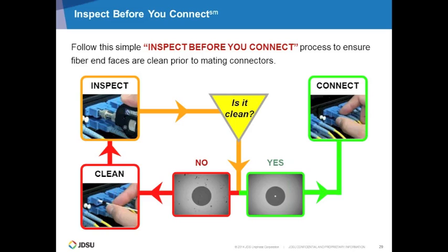Continue this procedure till the connector is passing or is satisfactorily passed. Right now, the inspection software gives you an easy pass/fail, so that's easy to determine if you have acceptable or not acceptable. A lot of people are asking, why shouldn't I just clean and not inspect?